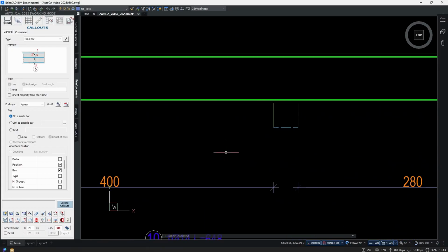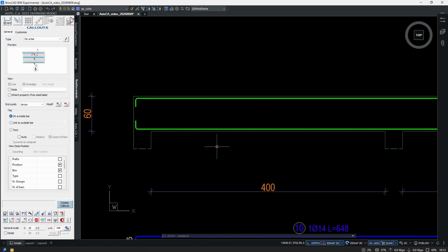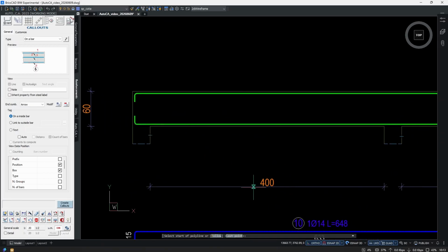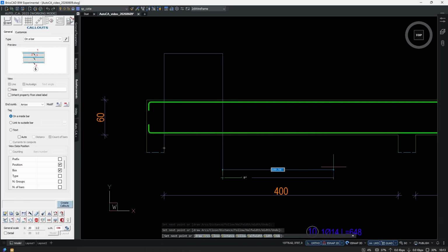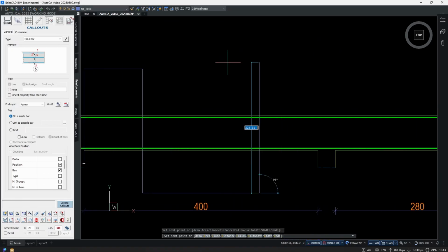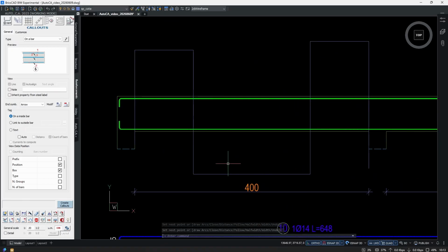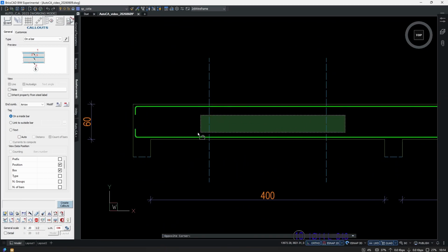To continue, we're going to create the 3-zone stirrup distributions. But before that, I'm going to define those 3 zones inside one single segment of the beam. So we have 400 centimeters, one segment. So we will need for one zone 100 centimeters. The middle zone is 200. And the last one is 100 again. That's it. These are our 3 zones. I will leave 2 markers here and I give them line type.